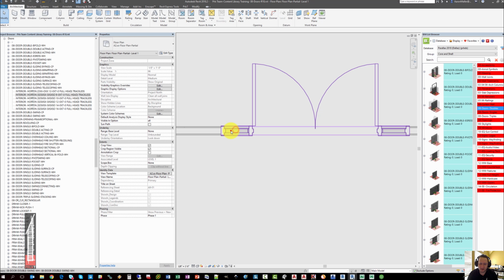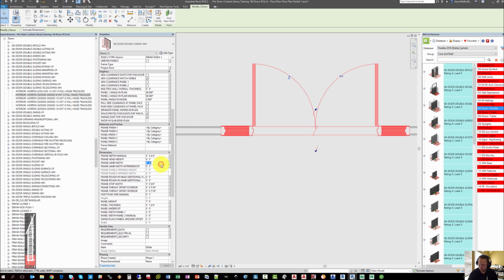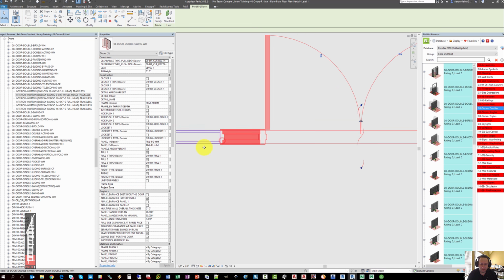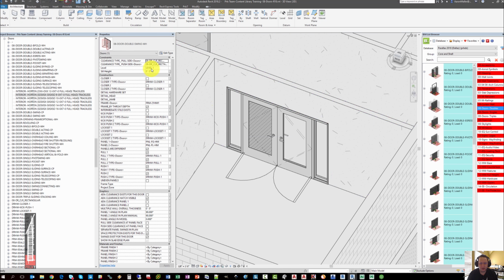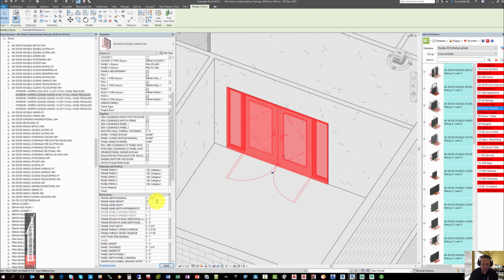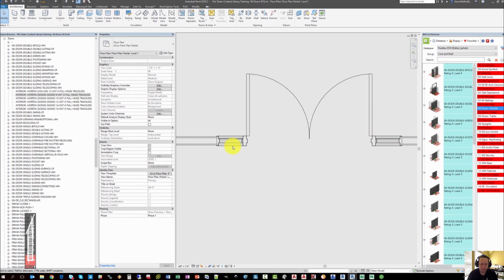The simple version is the jamb width will basically control the face width of the door frame. So if you decide you'd like a 1-inch frame instead of a 2-inch frame, changing it will actually make the frame 1 inch. If you'd like the head height to be 4 inches for a masonry wall, you can basically say that you would like the head height to be 4 inches. This means that your door type legends can basically say refer to door schedule, and you don't have to have different details for every different size frame that you have.